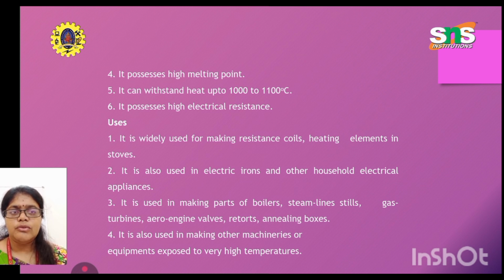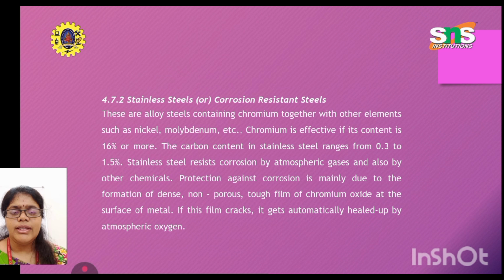Uses: it is widely used for making resistance coils and heating elements in stoves. It is also used in electrical irons and other household electrical appliances. It's used in making parts of boilers, steam lines, stills, gas turbines, aero engine valves, retorts, annealing boxes. It is also used in making other machinery or equipment exposed to very high temperature. So this plays a very important role when very high temperature is involved.